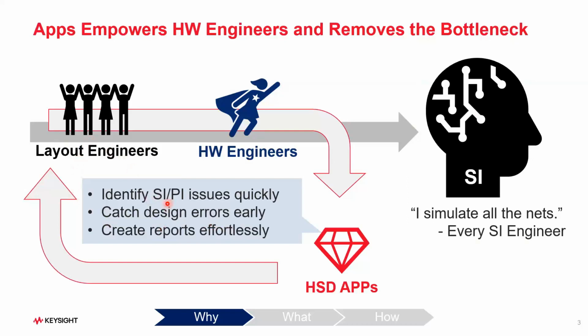As many of you are aware, when you see an impedance mismatch, the best thing we do is change the track widths using any IPC calculators. But we should know, once we finish the board file on my layout, which of the nets' impedances are not matched, or which segments are not matched, or what discontinuity is happening on my layout file. So you need some kind of quick analysis on the layout after routing. Though you follow the IPC calculator, there are instances where you might tweak the parameters to adjust the real estate on your layout file. So the idea here is to analyze on the fly between the layout engineers and the hardware engineers, and you can quickly identify these errors, modify this data with respect to the layout constraints and update, and again run the analysis.